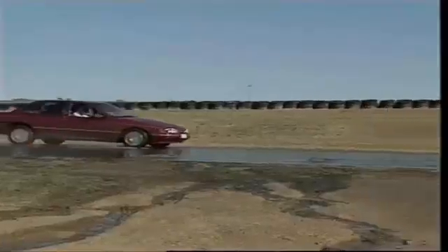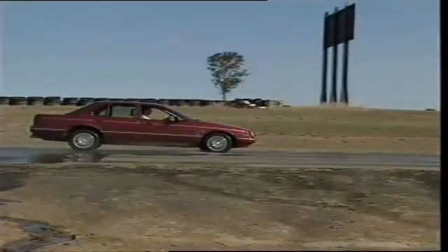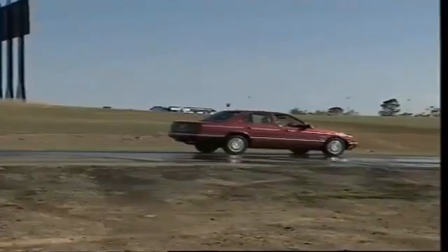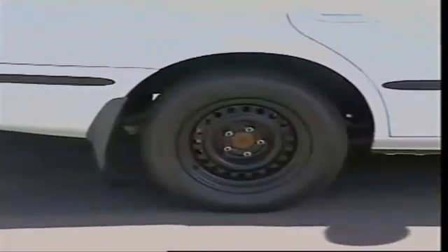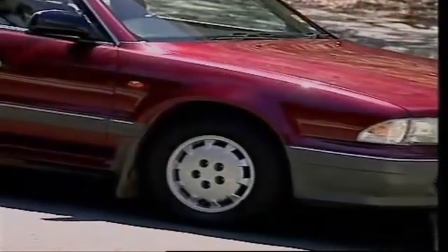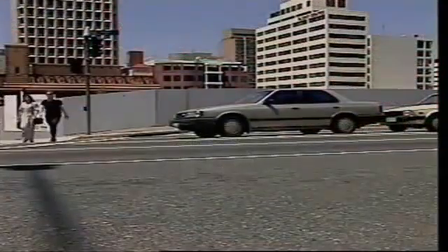Applying the brakes causes the front of this vehicle to dip. This causes greater tire-to-road friction on the front tires and less on the rear. This kind of change of load is called load transfer. So if equal braking force is applied to the front and rear wheels, the smaller rear load can make the rear wheels lock and perhaps skid. The braking force applied to the wheels needs to be adjusted to allow for changes in load.